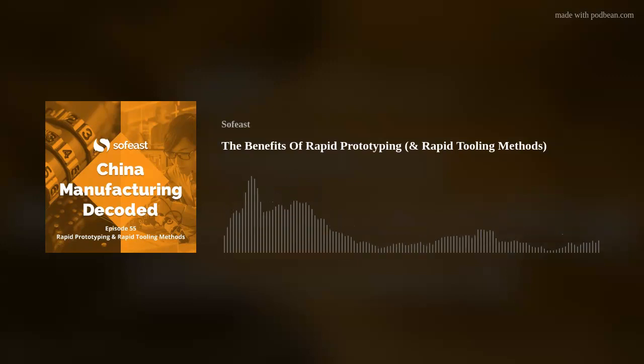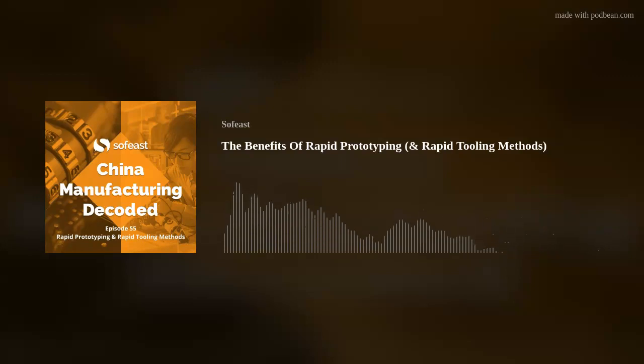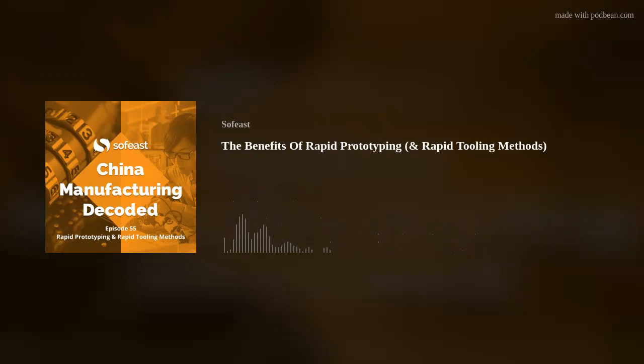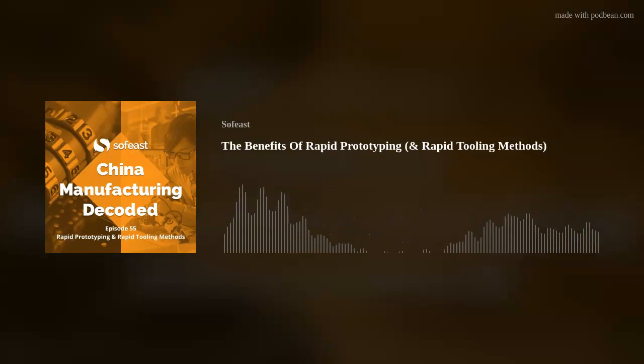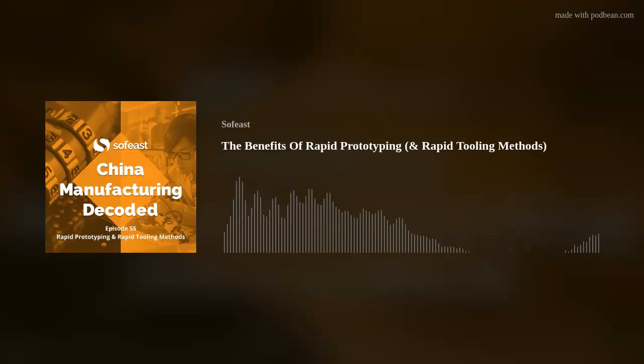Then the other extreme that I mentioned before is CNC machining. So you have a block of material, and then you have typically a three-dimensional arm that goes around, positions the cutting tool, and zoop, removes some of the material, right? This comes with high precision, so it can be done with pretty tight tolerances.